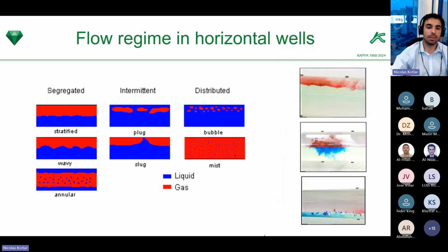In terms of flow regime, horizontal wells can be very complex. In most cases, we assume a level of segregation, and depending on the fluid velocity, you can go from fully segregated, what we call a stratified flow, to a dispersed flow with higher velocities and higher shear stresses, and ultimately, at very high velocities, even mist flow, but this is not a very common condition. But in any of these scenarios, imagine a centralized spinner here on the low side of the pipe, it would not be convenient.